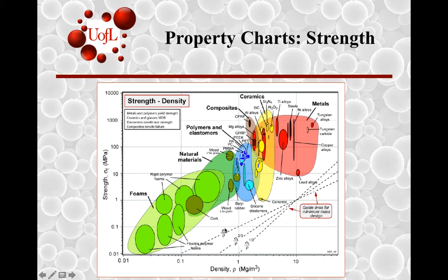And we had these various guidelines for minimum mass design depending upon the shape, whether it was a tri rod, whether it was a different cross section, or whether it was a thin sheet. So in the last class, we had looked at the fact that, depending upon the constraints and their magnitude, you had a line with a slope of 1.5 that was placed over here related to this material index. Without taking into account shape factors, the materials below this particular line would all be eliminated. Those above this line would be under consideration.